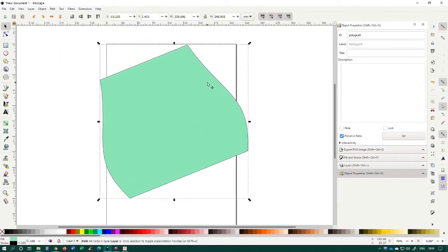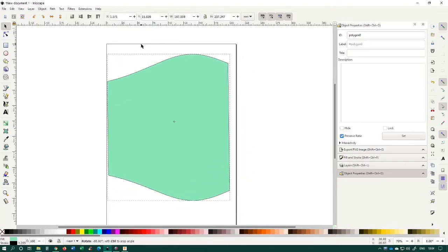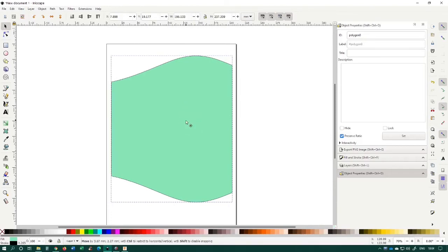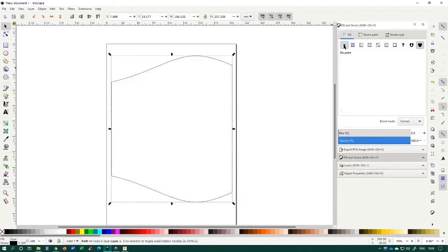The way to do this is to first break the shape at the corners. Before you do this, you may want to set the shape fill to empty. Use the Node Edit tool, then select the node at each corner and use the Break at Selected Node button.